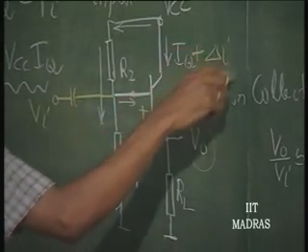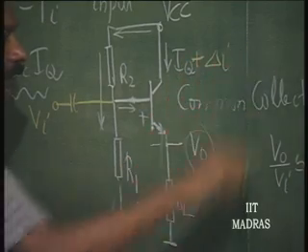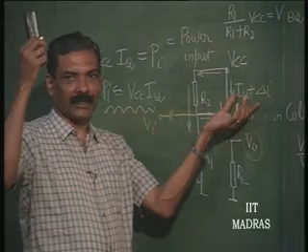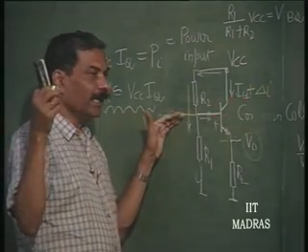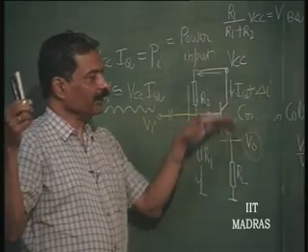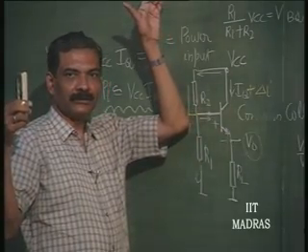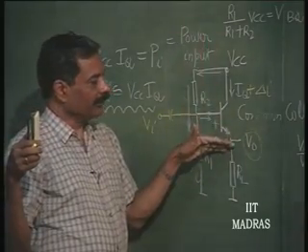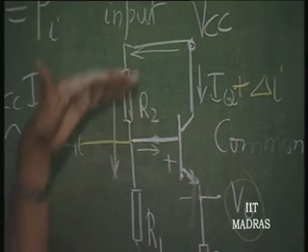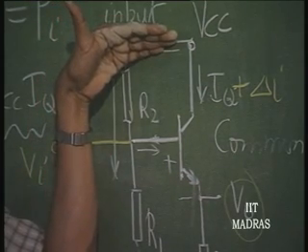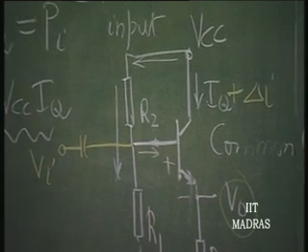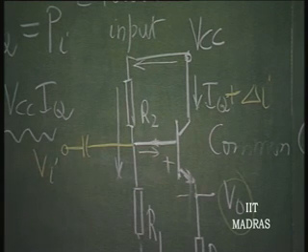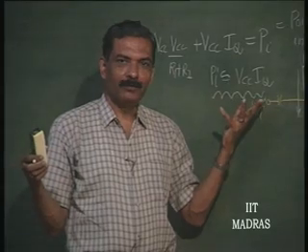So, this is going to be either equal to 0, or on the other side it can keep on increasing, there is no limit actually. As long as Vi keeps on increasing, this current can keep on increasing without any limit. Now, what is the maximum current ultimately it will lead to, where Vi becomes maybe almost up to VCC, because this might be coming from the previous stage, and the previous stage is also connected to a supply like VCC, and therefore, the maximum voltage you can have there is at most equal to peak voltage VCC.